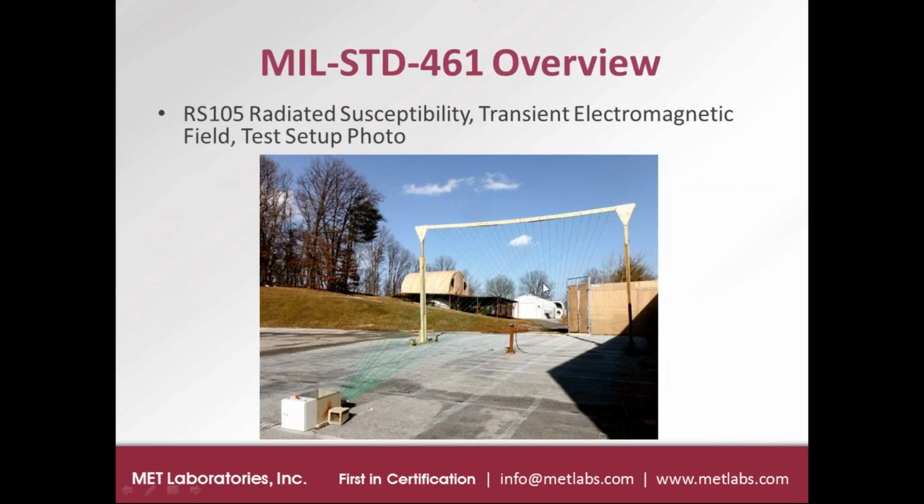If it's possible to accomplish the height within a test chamber, and also to meet an additional clearance off the top of the lines, between the top of the lines and the absorbers of the test chamber, which you can usually find guidance on from the generator manufacturer, it is allowed to do this test inside of an EMC chamber. However, it's usually limited in the EUT size that can be tested there.